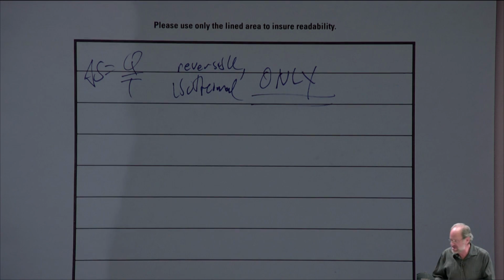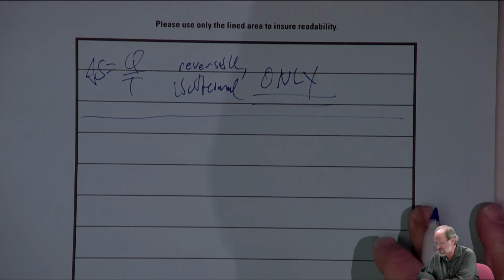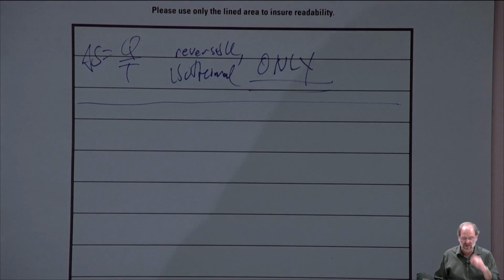All right, so now let's get back to what we're talking about now, which deals with isentropic efficiency. Sometimes this is called adiabatic efficiency for a steady flow device. Now, specifically, we're talking about pumps, turbines, and compressors, right? This is what we talked about last time. And this new term has been defined for you called isentropic efficiency. It has nothing to do with the thermodynamic efficiency, right?